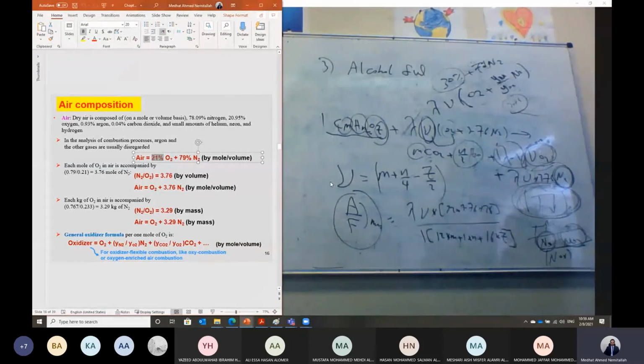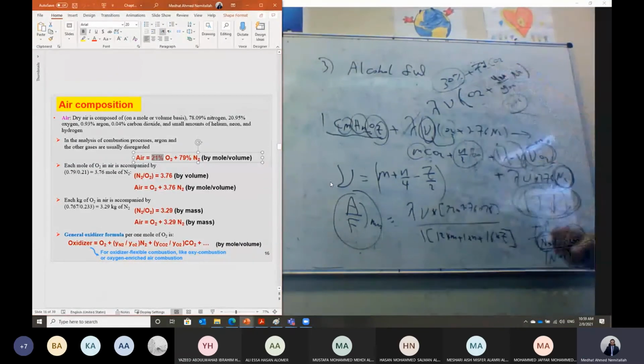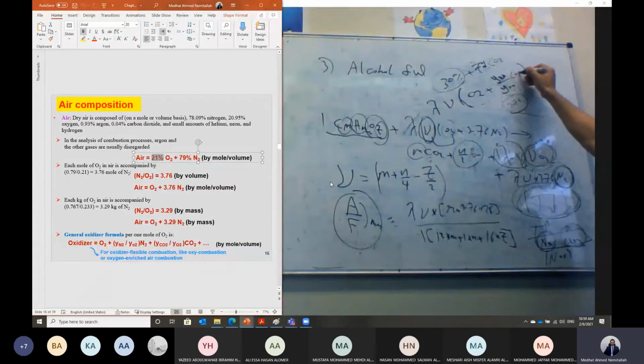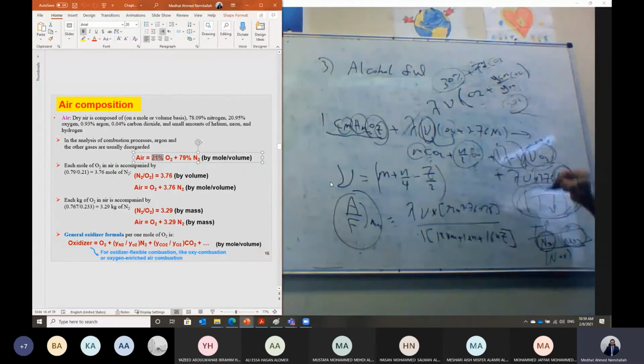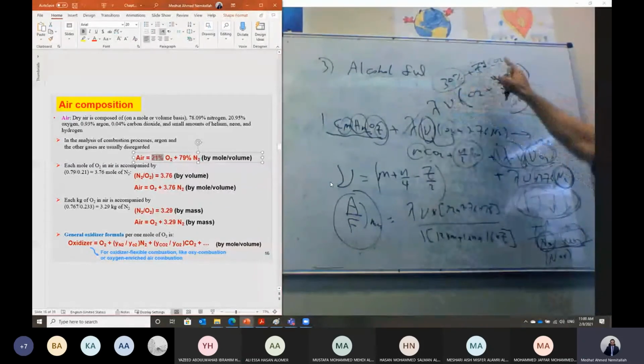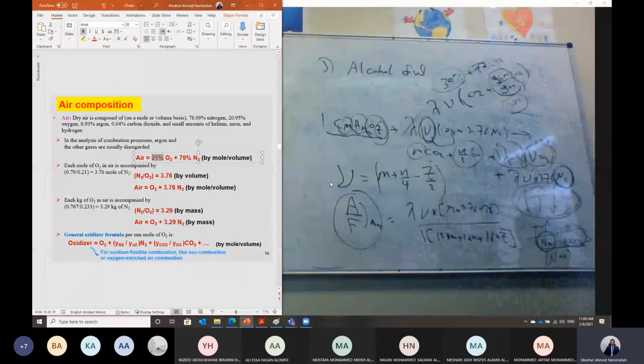But if it is carbon dioxide, it doesn't matter. In case of oxy combustion, we don't have nitrogen. Usually we recirculate some amount of CO2. So here, instead of nitrogen, it will be CO2, and this is the mole fraction of CO2 divided by the mole fraction of O2. Let's say we have an oxidizer of 30% O2 plus 70% CO2. So the oxidizer will be O2 plus YCO2 divided by YO2 from the CO2. Whatever this ratio is, you can just make it.